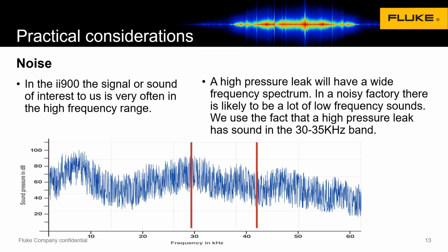Okay, so air leaks are a complex thing. They're not going to be at just one frequency. That's a real disadvantage with traditional ultrasonic tools, because they will typically only sample at a particular frequency. All sounds, including air leaks and gas leaks, have a complex sound signature. It's frequency versus loudness, or sound pressure level. So what our product allows you to do is take a couple of unique peaks and spikes and be able to focus in on those.